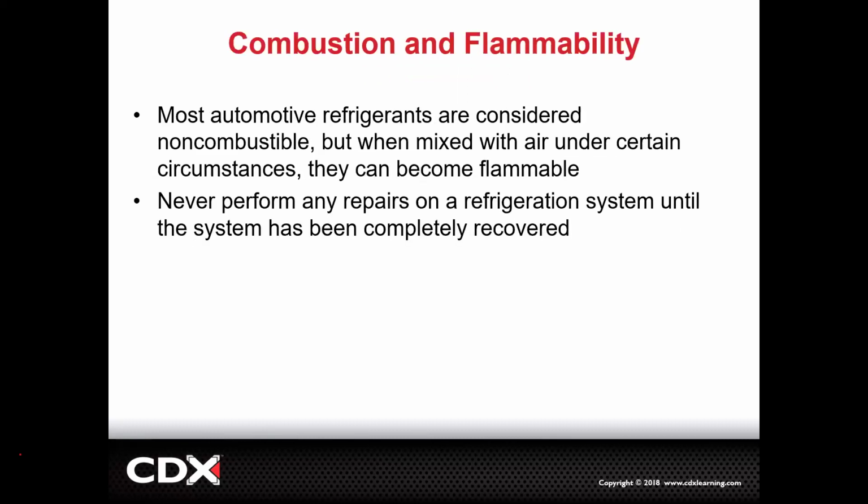Okay. Now, here is something that usually gets people kind of interested. Most automotive refrigerants are considered non-combustible. However, when mixed with a certain amount of air in the right circumstances, they can become flammable. For example, R1234yf is flammable. It's kind of like gasoline. You could throw a match in liquid gasoline and it won't burn, but if the gas is vaporizing, you have fumes and vapors, it can. It's similar, and especially with the 1234yf, the latest refrigerant is more flammable than any of the others before.